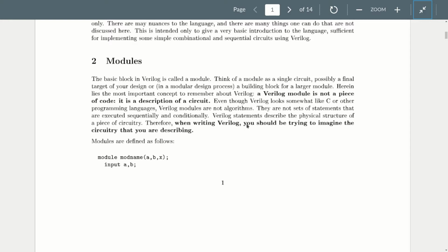So you can write your Verilog description, you can run it through a simulator, and it will show you what your circuit did. You can say, I want to feed in ones and zeros like this, and it'll figure out what the outputs are. But then optional Lab 8 will actually be able to take a piece of hardware and implement your circuit on it. So we'll talk about that on Thursday also.